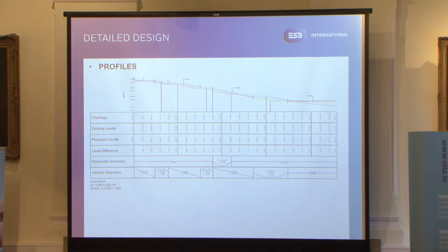The alignment and profile functionality is at the core of what makes Civil 3D such a great tool for us. They are our single source of data. And changes made to an alignment will also change the profile, its labeling, and any volume calculations or design that is done using it. Our model is the primary location for our alignments and profiles, and using a combination of data references and XREFs, we can share our data with other designers, which avoids data duplication.